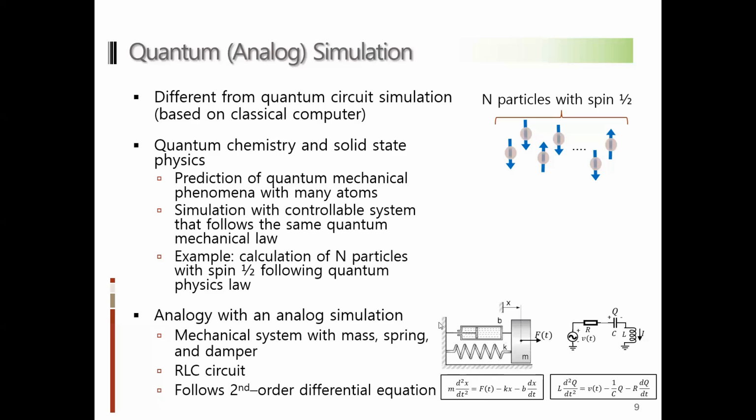But let's say that we have not only these three, but many dampers, springs, and different masses. The order of the differential equation is not so straightforward, but becomes more and more complicated. In that case, instead of solving this differential equation, you might choose to simulate or test this kind of system, and try to optimize it with the proper spring constant K, damping constant B, or different mass. If you know about mechanical systems, changing the mass actually requires some kind of machining. Or if you want to try a different spring constant value, it will also require a lot of